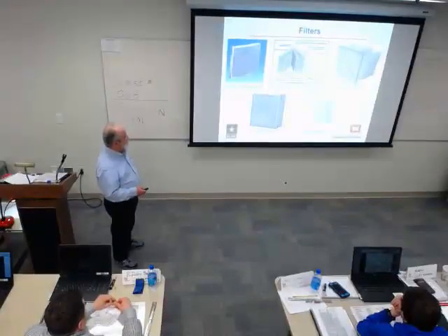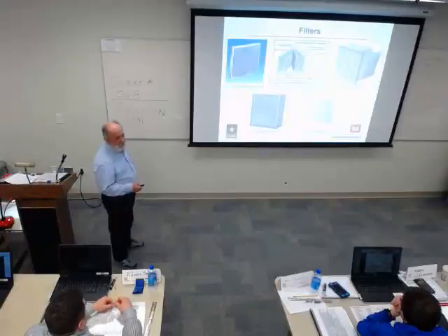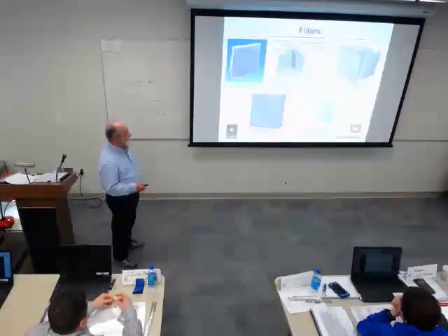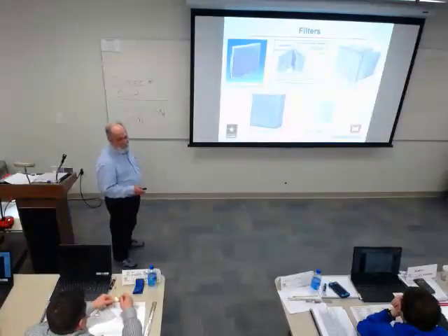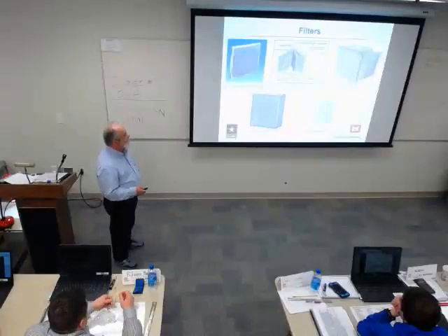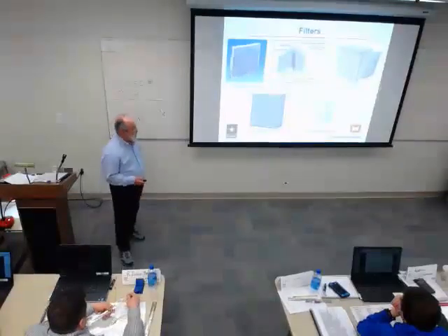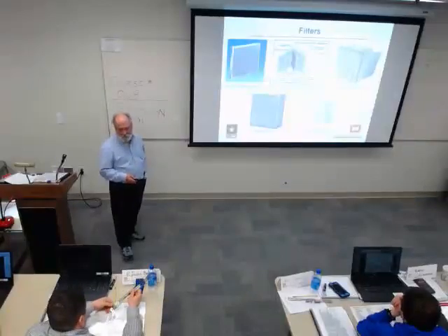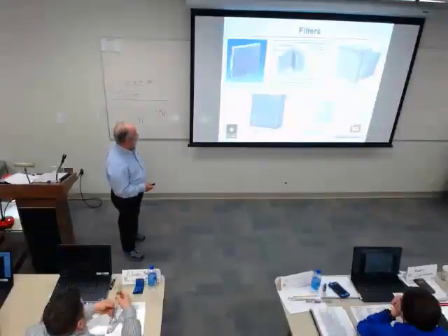Here are different filters. We have viscous impingement. These are often seen in residential applications. You can see through them. The idea is that dirt crashes into the fibers and it's coated with sticky stuff and it sticks. Another thing that they do is they build up a filter cake. That's really what ends up being the filtering element, the filter cake. That's true for all filters.